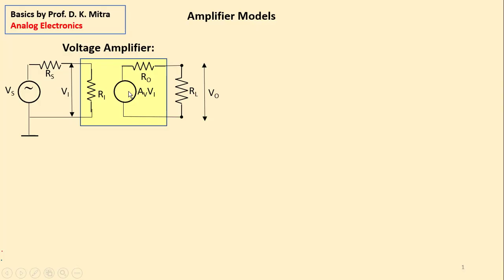The Thevenin equivalent calls for a resistance in series with the voltage source. This resistance is normally very small. I think in school you learned the source resistance of a battery, right? It is that resistance. It will always have a resistance, however small it may be, and it is normally small. So in the Thevenin equivalent of a voltage amplifier, there is an input resistance or impedance, an output resistance or impedance, and a voltage source.